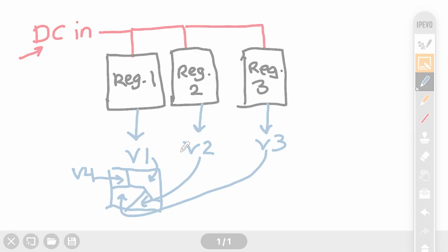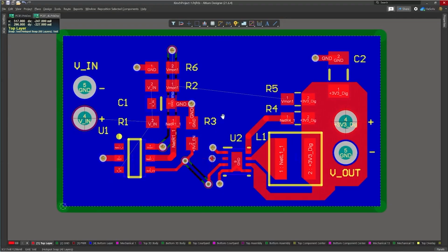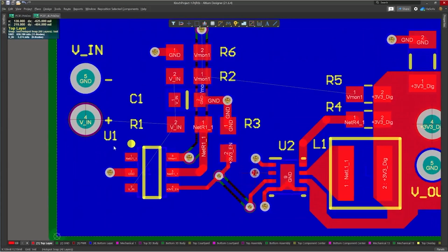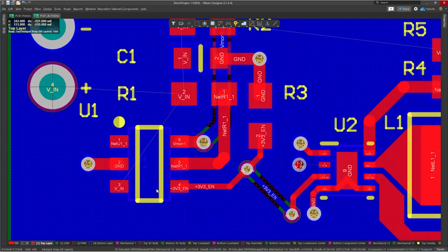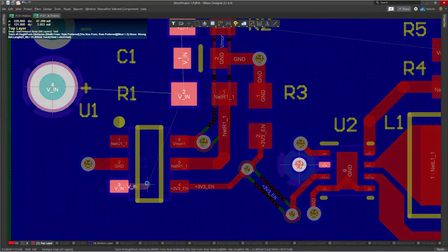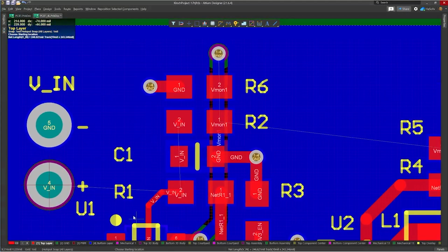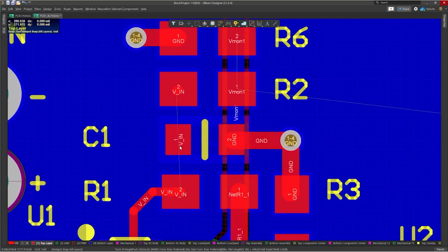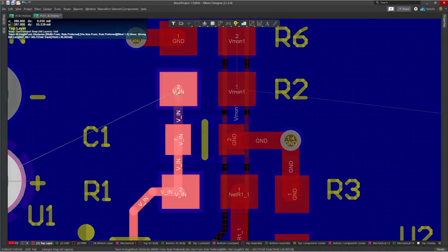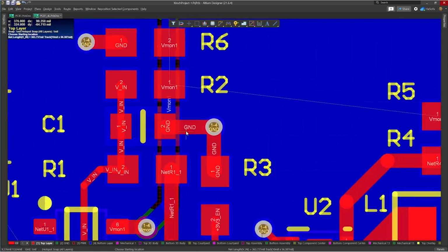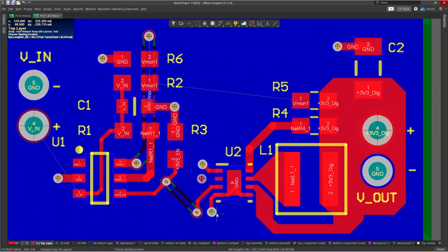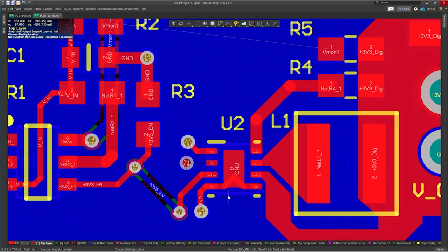Right, so we have a printed circuit board here, and in this design I will add some voltage rails, and that's just traces that provide the voltage I need. So what you do is you do your routing. Now, normally I don't like going under components, but in this situation, there's a lot of space under there, so that's okay for me. And the voltage rails are convenient because I can just route my traces directly to where my nets are, and I don't have to worry about doing a lot of extra work.